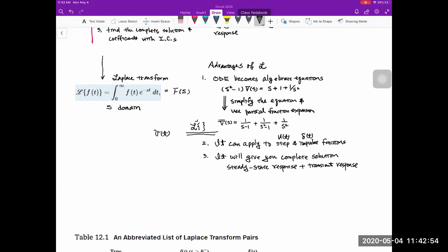The transient response normally will die away when we talk about the phasor domain. We talk about that three different kind of solution form. All of them has an exponential, and there's an exponential negative some power. And because it's negative, when time goes to infinity, all these things will die away. It's going to go to zero. So we only care about the steady state response if you're dealing with the phasor.